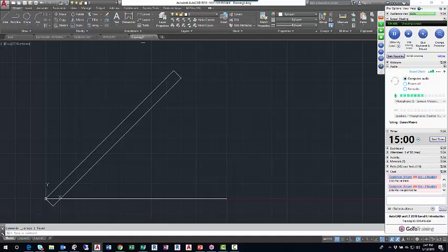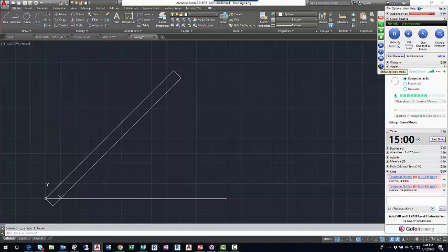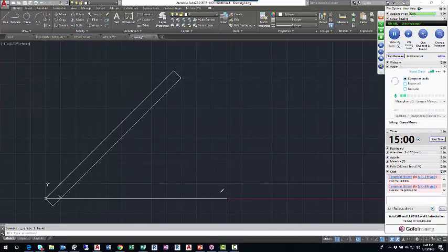So we're going to use the arc tool. I'll open up the drop down for arc. I wish I could pin it. I can't pin it. But the second method from the top is start, center, end. And there's probably more than one way that works, but I find this to be the easiest, start, center, end. And what we'll do is we'll start the start, center, end command for arc, and the start point will be the right end point of this horizontal line. This will be the start. I'm just going to put an S there, not a very good S.